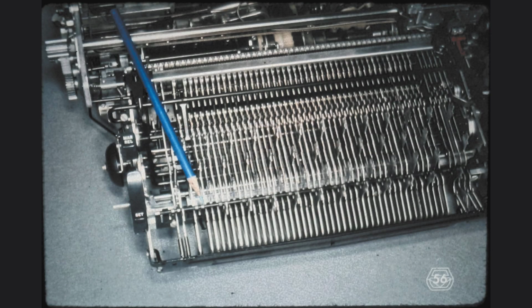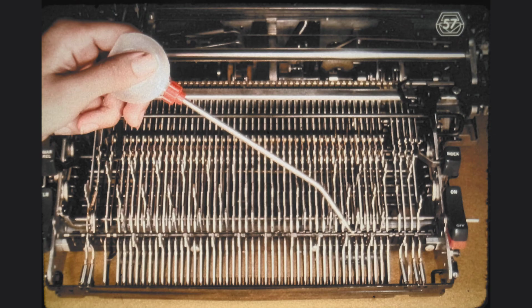Now locate this keylever upstop on your machine. It consists of a steel rod covered with rubber in order to dampen the return stop of the keylevers. We shall remove it next. Unfortunately, however, there are many times when the rubber is completely dry and stuck on the brackets or clamps which support it. The most practical way to loosen up the keylever upstop rod is to apply oil to it all across the width of the keyboard.